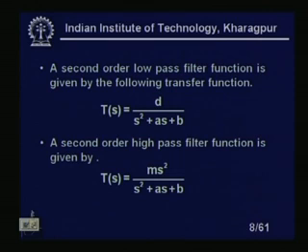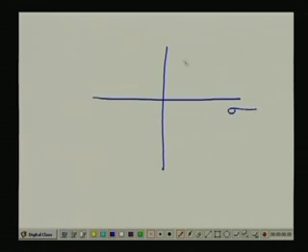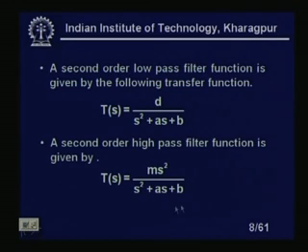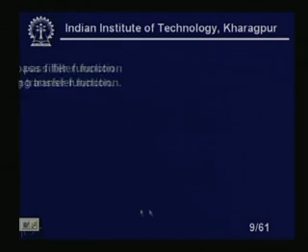Now, the pole zero pattern will look like, take a white page, it will look like the sigma j omega plane. So, it has complex conjugate poles and two zeros at the origin, right, double zeros at the origin, fine. So, this is our second order high pass filter function. Always please note that m, a, d, everything is to be realized by some resistance and capacitance, right, and op amp obviously will be there.